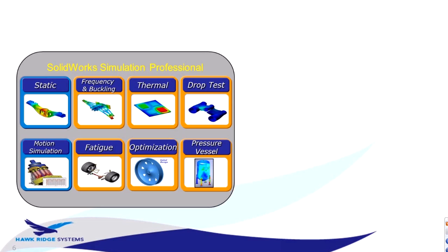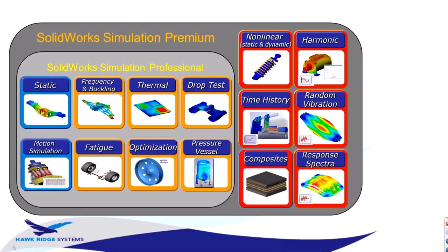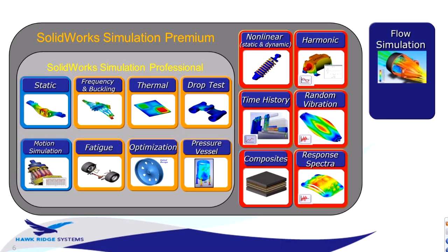It also introduces some other tools and functions. We're going to talk about something called Trend Tracker today. That's part of Simulation Professional. At top level, the stress analysis tool breaks down two doors for us. It lets us get into nonlinear situations, and it lets us get into dynamic loading: shock, vibration, impact, those sorts of things. Those are all FEA technologies, finite element analysis, all based around the same engine.